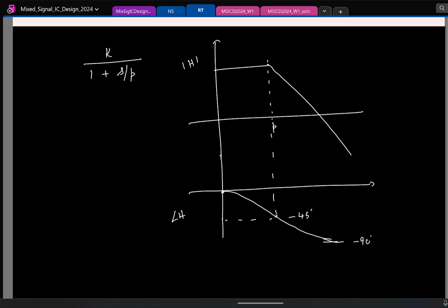See, now look at this, right? If I were to make a distinction between these two frequencies, from the magnitude plot, I can hardly make anything. But if I look at the phase, I can really say how far apart the frequencies are, right? So even if I look at the location of the pole, the Bode approximation does this, but in reality, it will do this, and the drop will be how much?